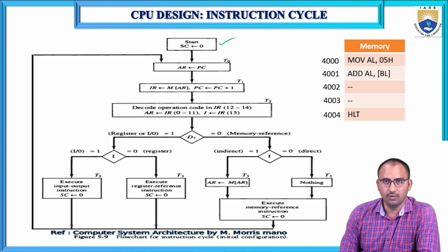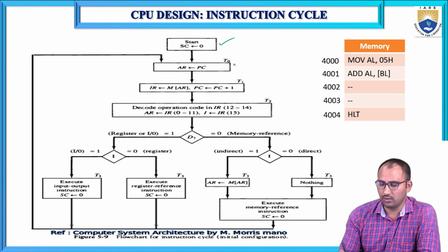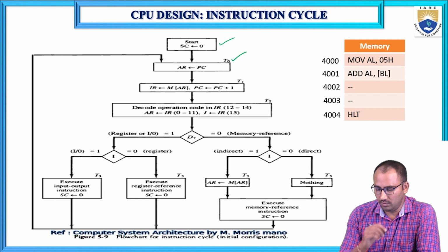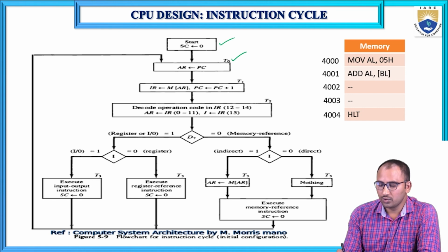Whenever we apply a clock to the sequence counter, it generates a timing signal T0. So what happens during T0? During T0, the instruction will be fetched.